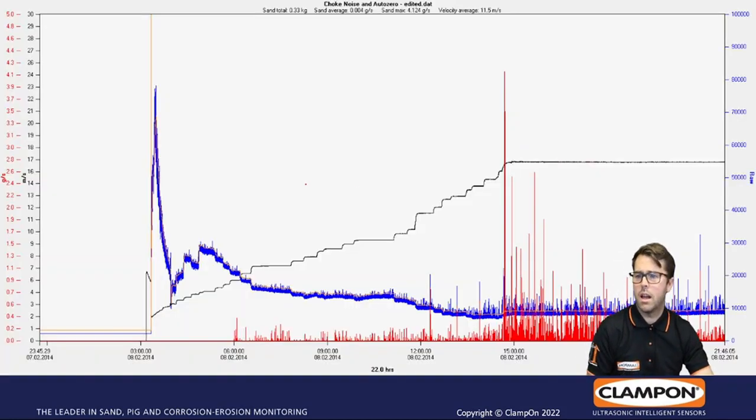This slide also shows a typical startup. As we can see here, the raw value level is up to 100,000, and you see a really high spike here. We got a lot of phone calls to the support center when this happened. They got a really high raw value and wondered what was wrong. Here they have maybe 2-3% choke, really high pressure over the choke, and you have really noisy sound from the choke.